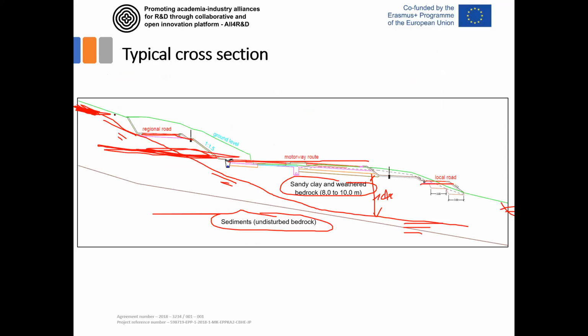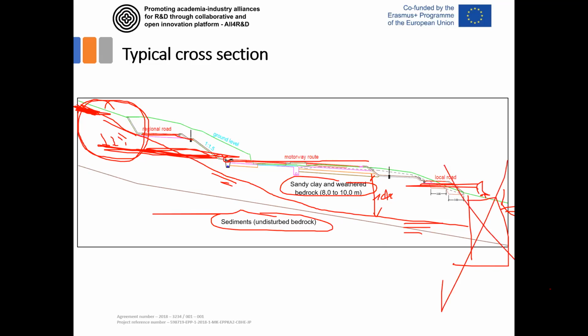So the idea is to collect as much as possible water here in this area of high water level, to collect water by horizontal drains and bring it out of this slope. Any other solution that will support all this measure with some large retaining walls and something are definitely out of option in this condition like now, where the increment of sliding is very, very slow.